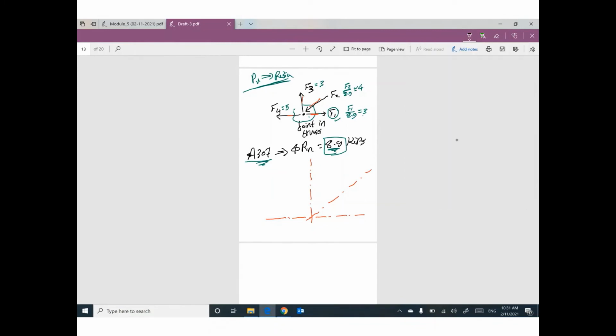So I decided this member will be angle, or double angle 6 by 6 by 1/2. So this width is 6 inch. The other one, I decided this member will be double angle 8 by 8 by 1/2. So this width will be 8.